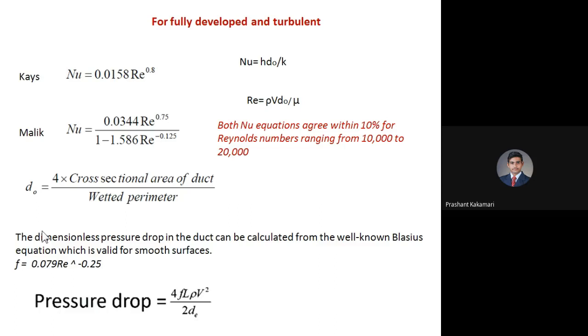If the pressure drop is very high, to generate the flow we need to go for pumping or we have to use blowers. Some external source of energy, or electrical energy, is required. That itself may be more than the energy the air heater efficiency takes out. So it is better that the pressure drop should be less, so that any external pumping or blowing is not required. For that purpose, we are finding this pressure drop.